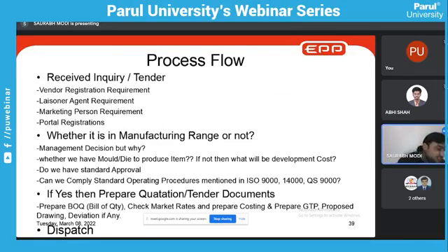But one thing that I forgot to mention is the FRP storage tanks and FRP pipes. These are mostly used when there is a problem of chemical compatibility. In SMC it is not there, but suppose you want to store sulfuric acid, H2SO4 or HCl, and if you store it in any metal storage tank, it will definitely get corroded within a span of 1 year. FRP always offers chemical compatibility. That is why FRP storage tanks and other items are used to a great extent.